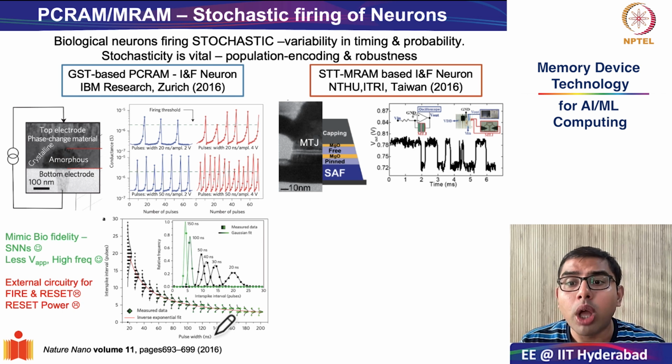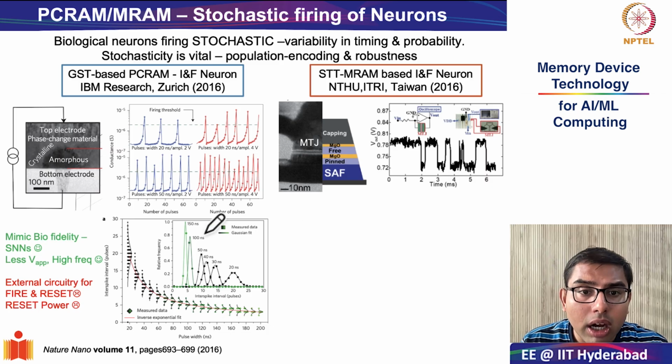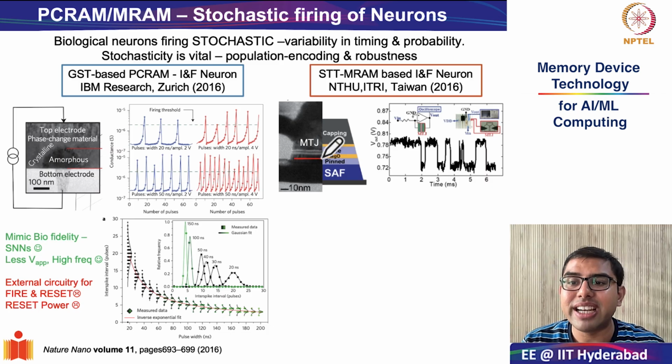Now, similar to biological neurons, the magnetic tunnel junctions which form the heart of STT MRAMs also do not switch deterministically.